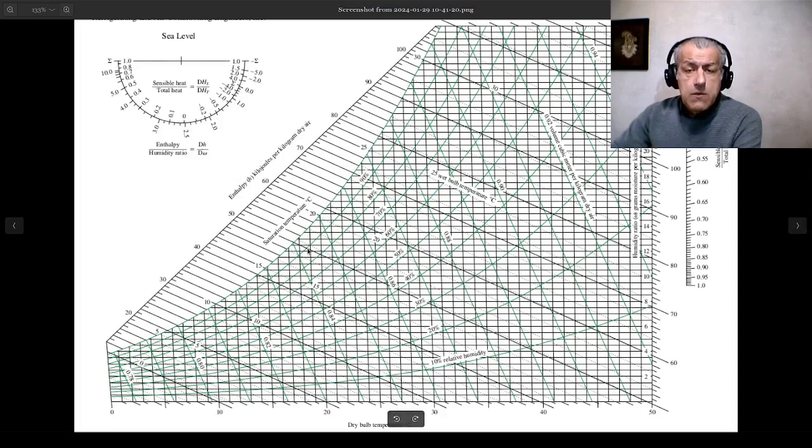And since we can calculate the other values just like we did, here we also can present them and know that for a specific temperature and humidity, we could read a specific humidity W from this vertical axis. And we could do it for our problem, and we would just shortly do it.